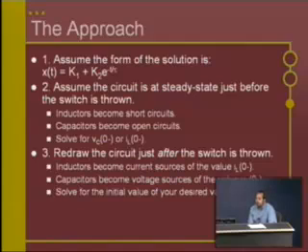And we're going to assume that the circuit, as drawn, has the switch in its original position and that the circuit has been at steady state, which has some important ramifications. If the circuit is at steady state, that means all of the inductors have shorted out, all of the capacitors have opened up, and the circuit is going to be in a particular kind of configuration.